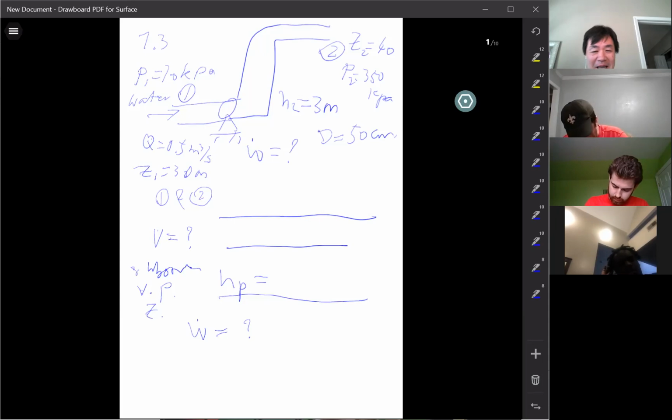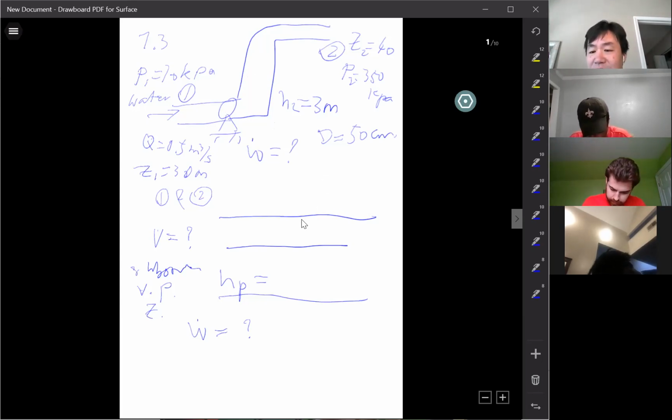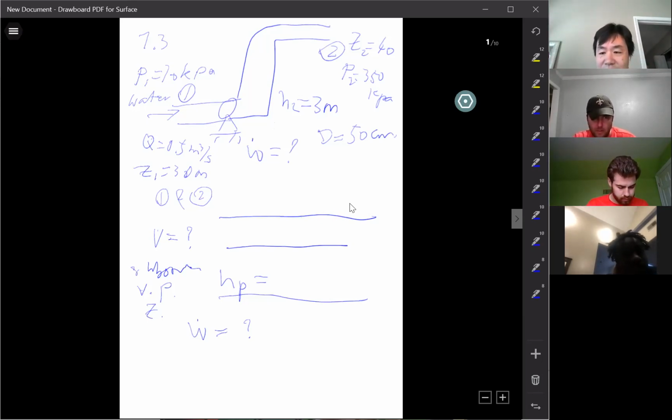Anyway, the meaning of this is you calculate an actual practical piping system like this, based on the information, based on Bernoulli's, actually we should call it the energy equation in the pipe. You should be able to calculate the power needed to supply to the system to make this work. Basically, that's the principle of pump selection: how much additional power you need to make it happen. So then you can find a pump to satisfy that. Is that good for this one?